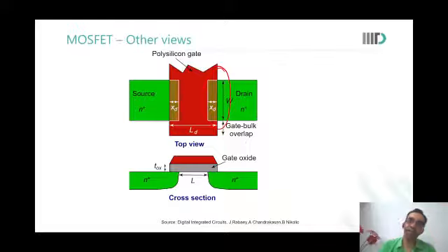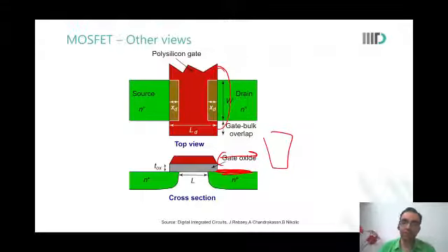No, but as a designer, you can control the spacing between contact and this. As a designer, you can control the overall diffusion region. So as a designer, you can reduce the density of contacts. And therefore, you can control the poly to drain, poly to contact, or let us say gate to drain capacitance.